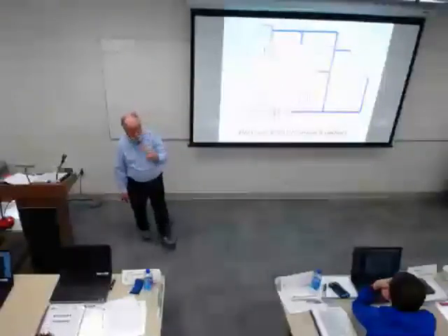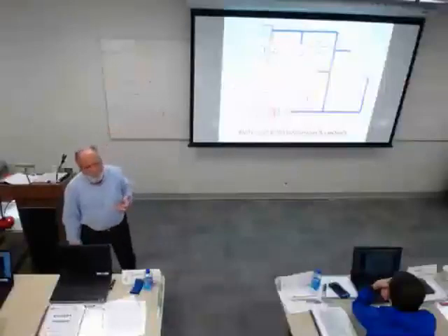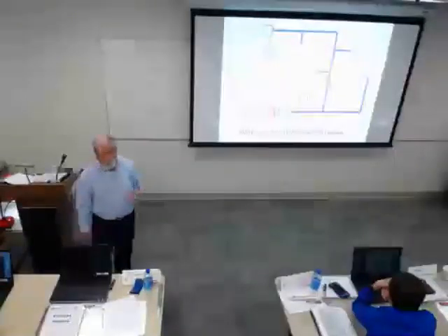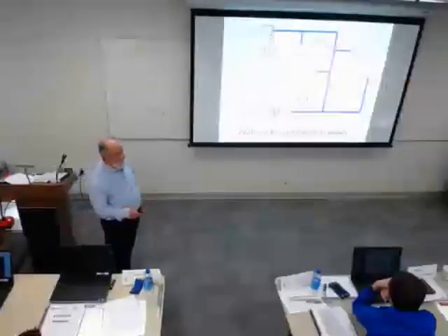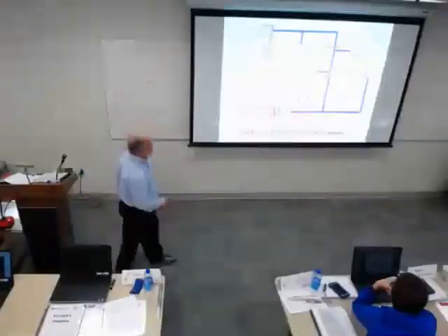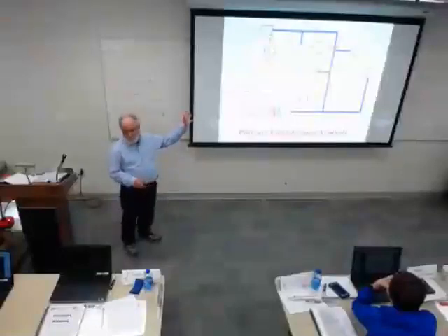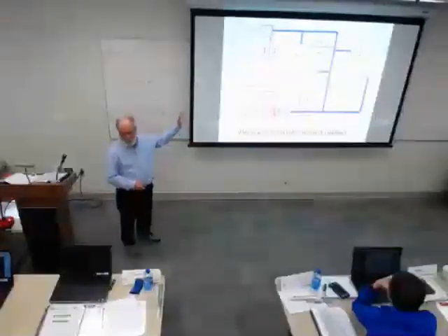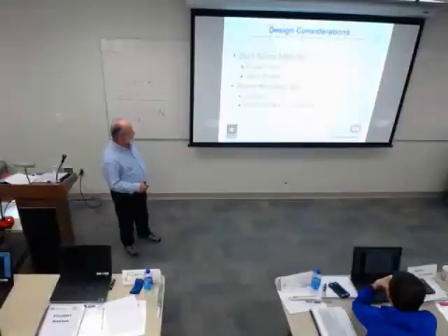As a designer for the systems that we use, which are generally small and pretty simple, I usually just use one class for the whole thing and put down in a note what the duct class is going to be. But those are the two things you'll see. It'll either be noted or it'll be symbols like that. And those are the standard symbols, and that's what SMACNA guys like to see.